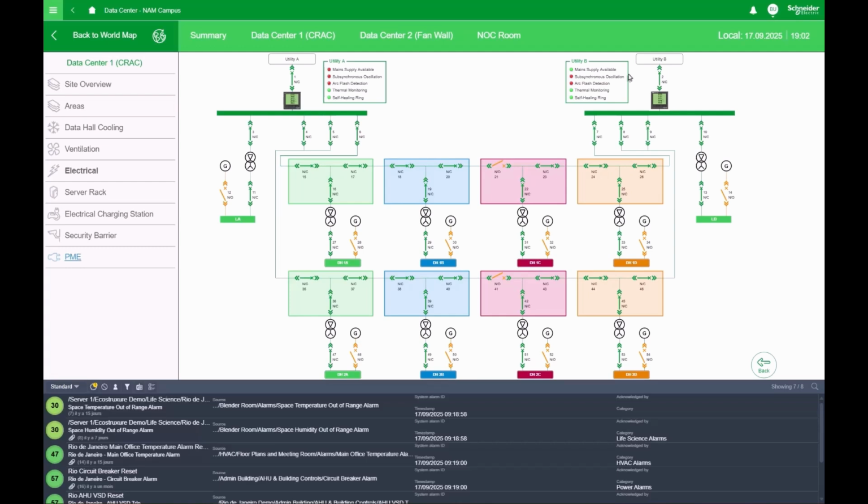We also offer subsynchronous oscillation monitoring within EcoStruxure. This is a relatively new phenomenon, at least for the data center industry, that we are seeing more and more as we introduce AI loads within our data center. And in addition, we can also monitor for arc flashes. Arc flash detection is actually a default coming from the EcoStruxure platform using templated devices. So altogether, we're able to provide 24/7 continuous thermal monitoring. We can avoid downtime and, of course, intrusive and dangerous inspections, and have instantaneous feedback about our MV system through the EcoStruxure interface.